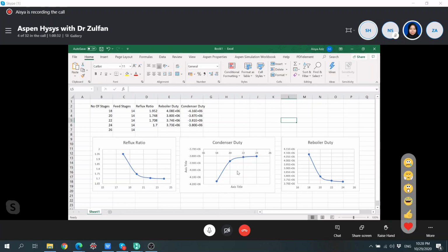Because for tall columns it's just capex, so they spend once and then let it run for 20, 30 years. But for the reboiler duty, because it's expensive, they have to pay this expensive amount of money every year. So they don't want that. They have a tendency in Europe to install tall columns. But in the US, on the other hand, they have big cars, petrol is cheap, and everything is cheap. So they have cheap energy, and they tend to design very short columns.